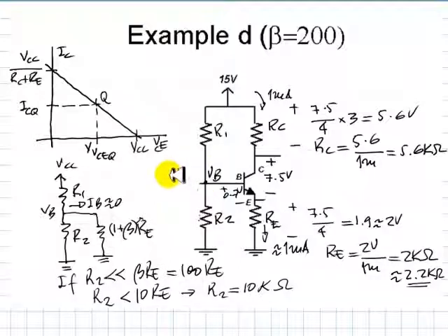And that is 2.9 volts, of course. But then think of it. Now we know the voltage here and we know the value of this resistance, which is 10 kilohms. Of course, we can compute this current I2, which is 2.9 divided by 10 kilohms.